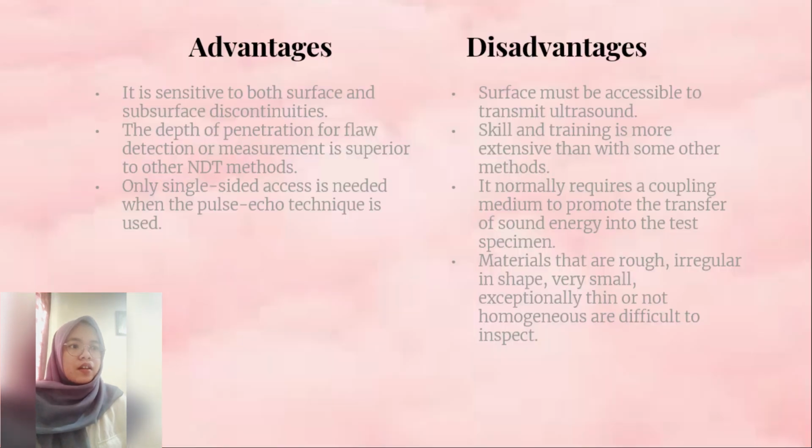The advantage of UT is that it is sensitive to both surface and subsurface discontinuities. The depth of penetration for flaw detection or measurement is superior to other NDT methods. Only single-side access is needed when the pulse-echo technique is used.